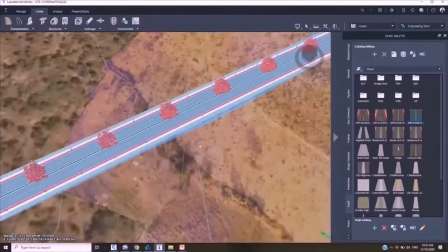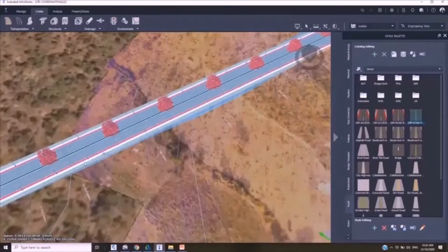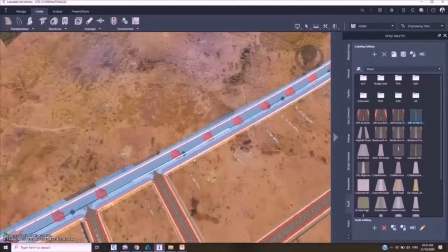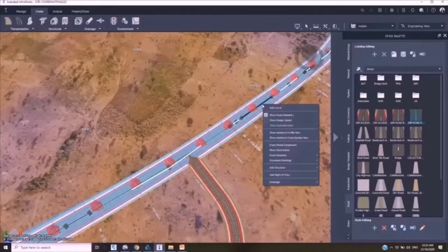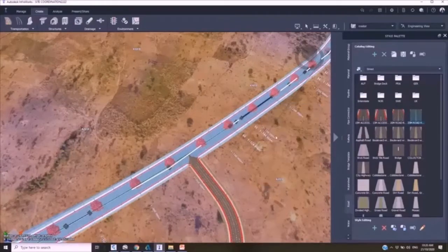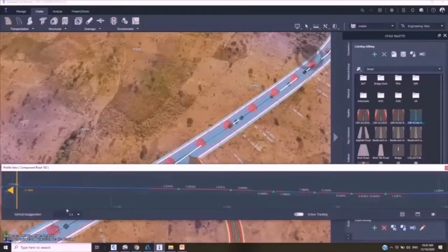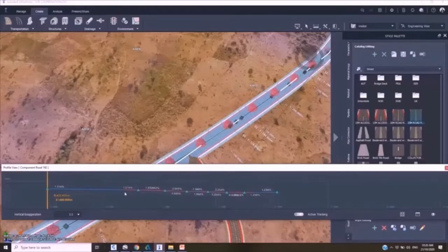So at this level, I can observe the condition of my chainage intervals as well as the curve details and change the parameters. In order to see the profile conditions of this created road, I'll right click on that road and click on show stations in profile view. So from the profile view, something I can always work in Civil 3D, I can see the condition of my details.